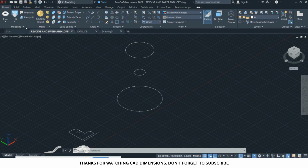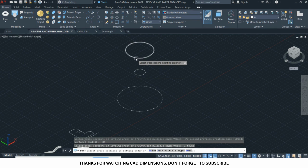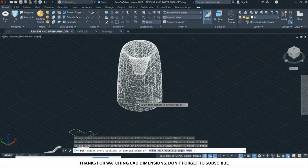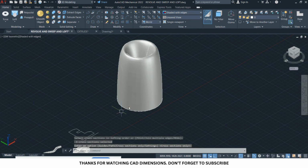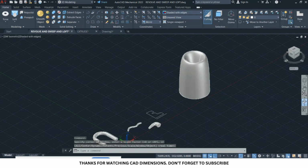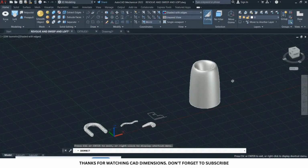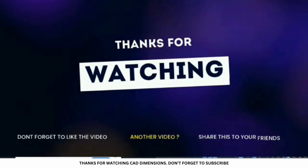Okay, so let's try this time around lofting in a different orientation. If I select this, I select this time around the top one as the second, and then I select the last one. You realize that the loft goes inside this time around. If you want to see the loft you've done, you press enter twice, then you're able to see it. You can now rotate and see what you've done. Okay, so guys, this is where we end the lesson on the basics.